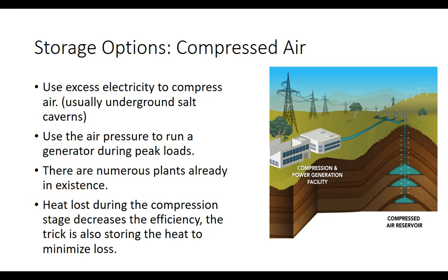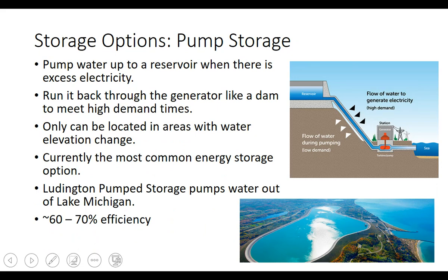So now you've got your compressed air underground, you've got your heat stored someplace else, and when you go to release it, you heat the air back up by blowing it through the gravel, and therefore it's heated back up to where it should be. When you release it, it's not freezing all your components. So that's one of the tricky parts of this: the heating and cooling, and keeping track of that heat, because otherwise you're going to have some issues. So that's cool. It's not the most efficient process, but again, we're just trying to avoid throwing away energy if we can.